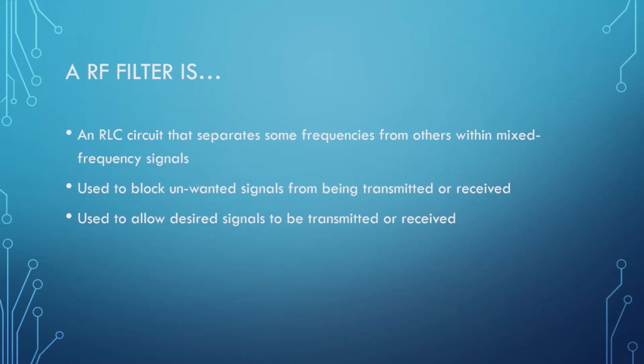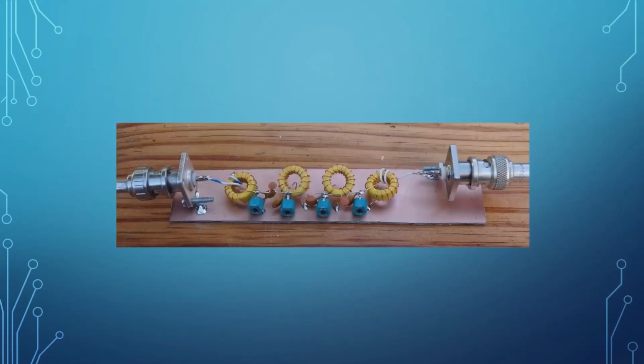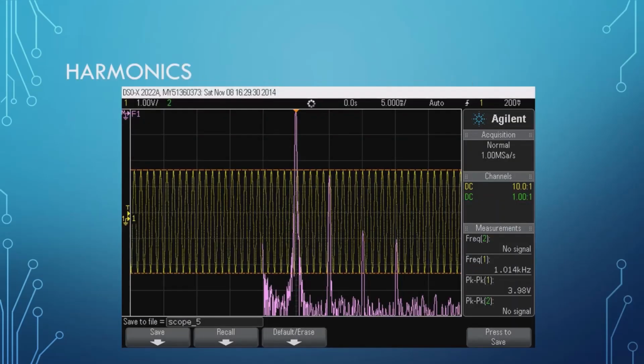We're going to be mainly looking at low pass filters, but these are some examples of different home-brewed filters. The first one was made with air wound cores. This one's made with toroids. And here's another one that's using capacitors that you can adjust to trim it. We're going to be building something similar, but at the surface level, so we won't be using adjustable capacitors. We'll be using fixed capacitors based off of the data sheet.